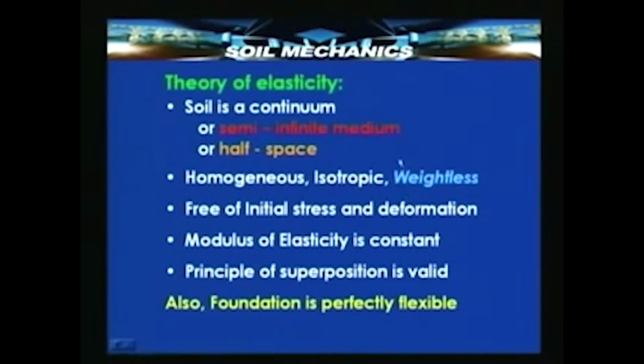Now, one more important assumption we are making about the medium, and that is it is weightless. Let us see the importance of this. Why is the assumption of weightlessness important? It is important because we are interested in the incremental stress that is being caused by the load that is applied externally on the surface of the ground. The weight of the medium, which is introducing a stress at any point given by gamma z, can be easily calculated if you know the depth z.